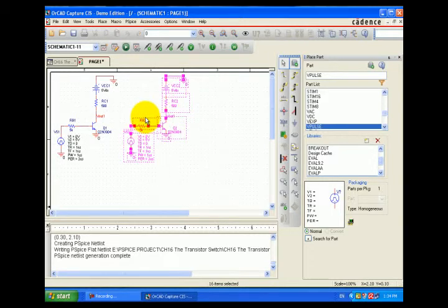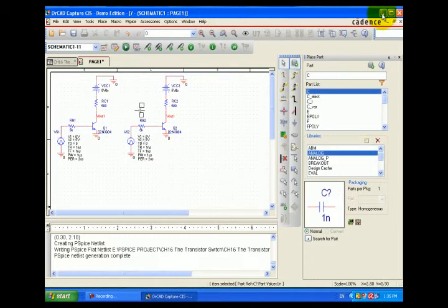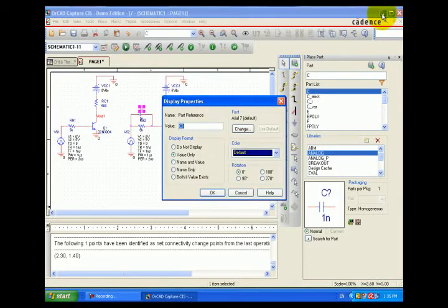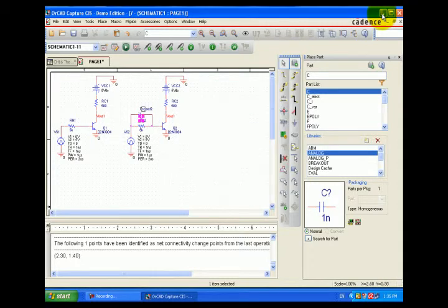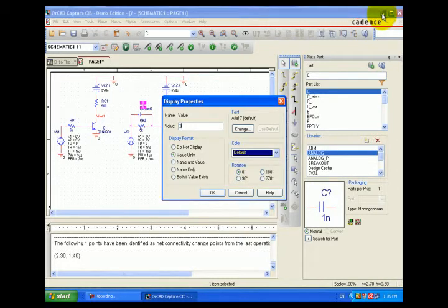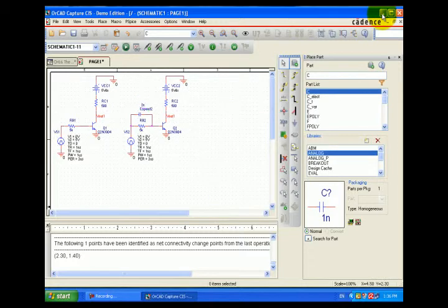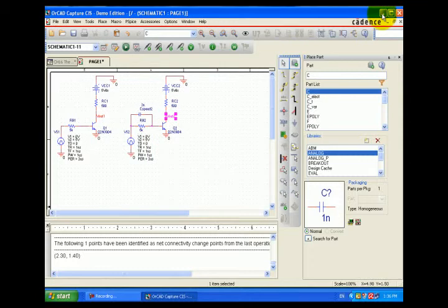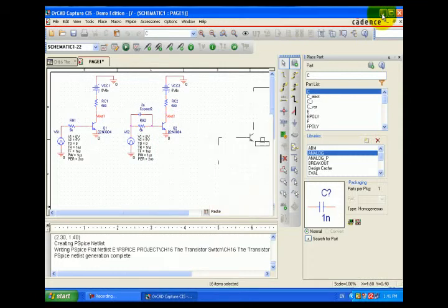Copy paste another circuit. Make the speed-up capacitance in the feedback of RB2. In the time domain, the capacitor passes the voltage change.